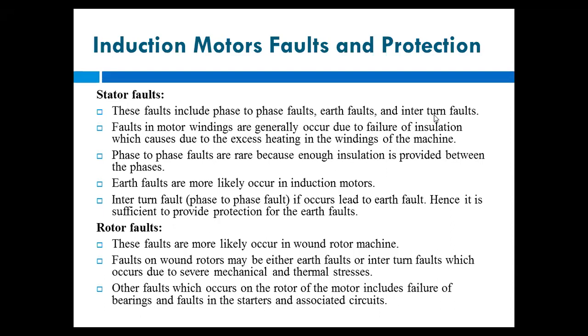Okay, so faults on wound rotors may be either earth faults or interturn faults, which occur due to several mechanical and thermal stresses, because we are using brushes. Okay, and slip rings are there. So due to slip rings, there may be some mechanical and thermal stresses, because we are connecting the load by using the slip rings, right?